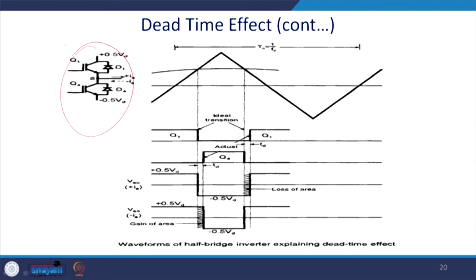You have studied the effect of the source inductance in basic power electronics, where you have essentially an overlap angle between the two thyristors, called mu, and in between there is no power being transferred because of the shorting of one leg of the thyristors. But since the current was low, the shorting was not a problem. Here, if the short occurs, then your high current will flow and the DC bus will sink. So, that is a great challenge itself.